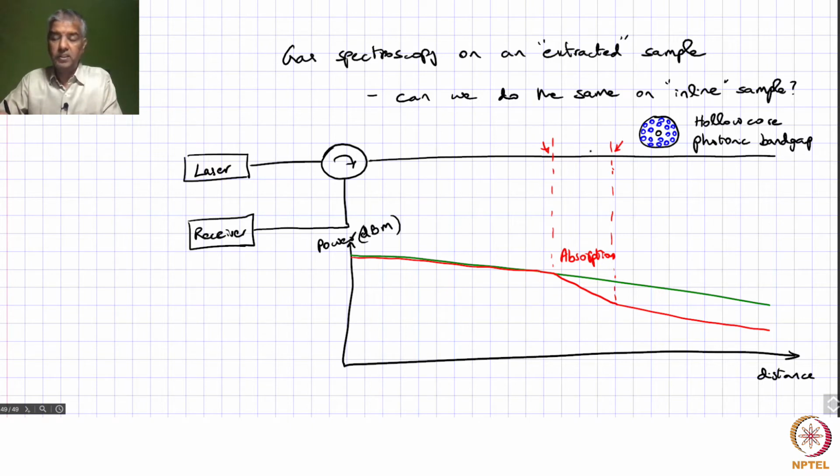Now, of course, we know using OTDR principles, we could potentially get spatial resolution of a meter, and this can be available across even 10 kilometers sort of distance. So, essentially we can roll the fiber out and figure out the constituent gases in that environment by doing the corresponding spectroscopy, married with this optical time domain reflectometry principle.